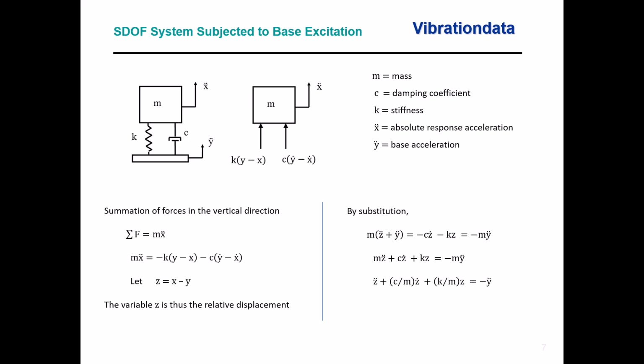And there are certain properties of that system, such as its natural frequency and damping. Depending on those properties, as well as the nature of y double dot and its characteristic, the spring mass system may have dynamic amplification, like resonant amplification, where x double dot peak is greater than y double dot peak.